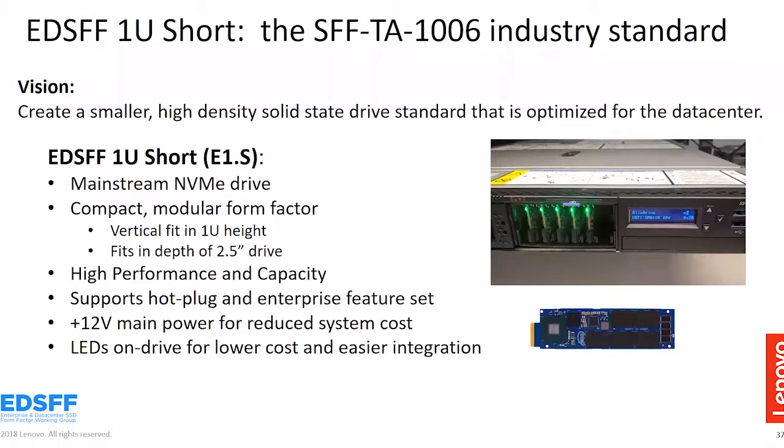It's very high capacity and performance. It's actually significantly larger than an M.2 to give you more placements of flash, at least 4 to 8 more placements, depending on what your M.2 design is. And then it supports hot plug and the enterprise feature set. So this connector is robust. It's going to run up to, I think, 112 gigabits per second is how fast you can run this EDSFF connector. It has been tested. It's already been run.